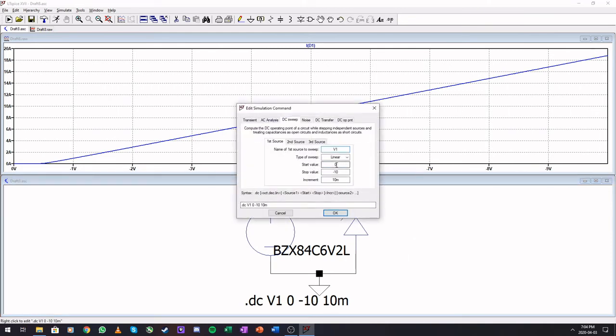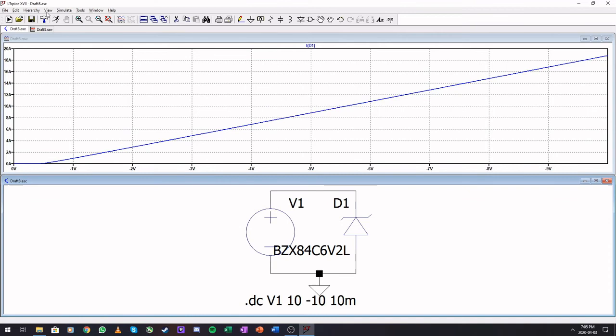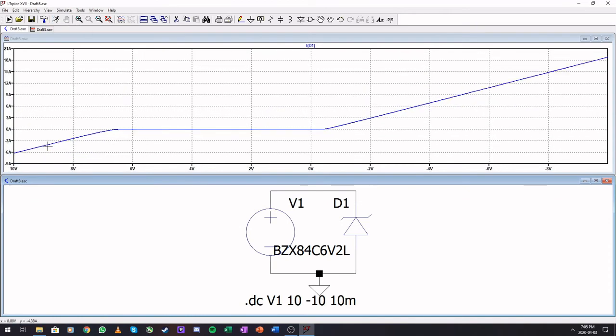So for the Zener, since it is important for the directions, we can probably find the whole transfer curve. So yeah, switching on at 6.2 and beside normal diode functionality. And that is it for the DC sweeps.